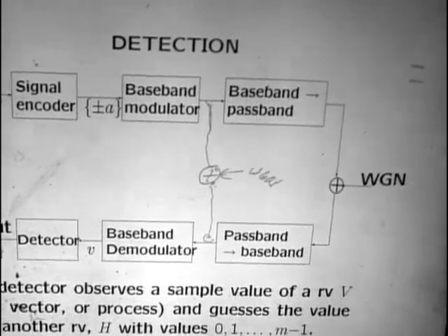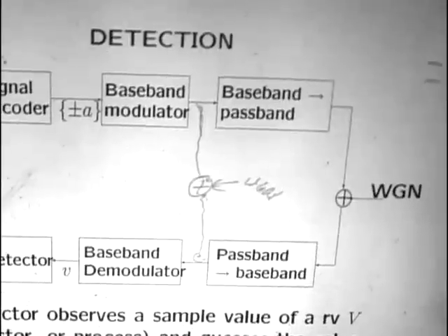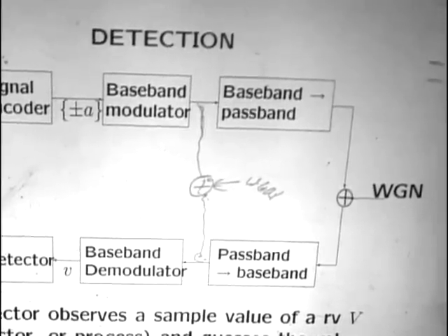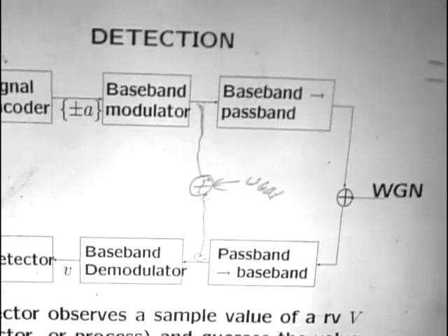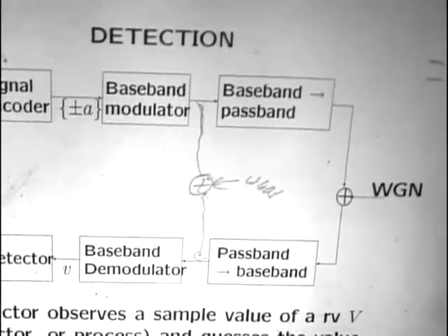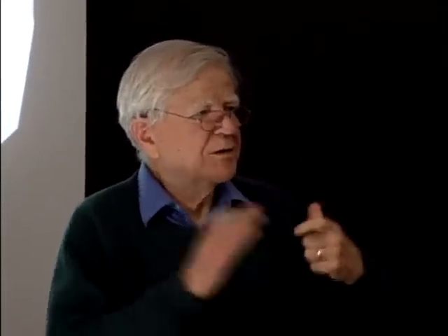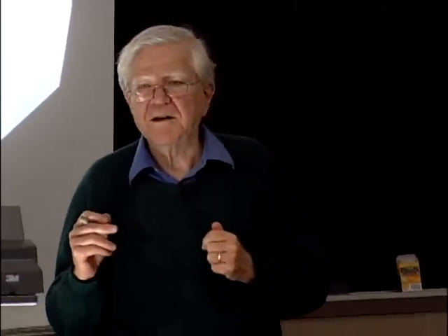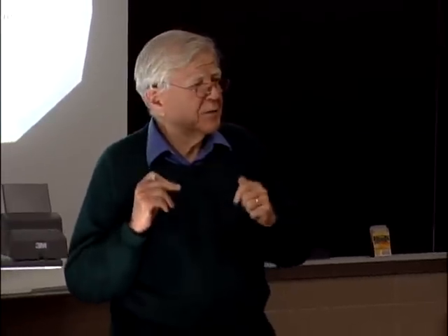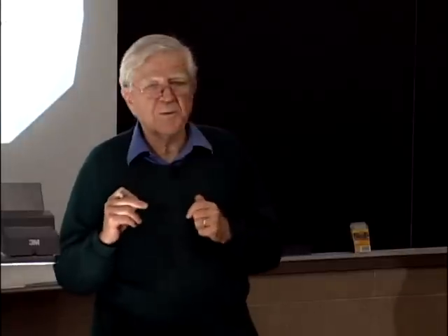We said a neat thing to do was to use a square root of Nyquist pulse at the transmitter. When you use a square root of Nyquist pulse at the transmitter, you have orthogonality between the pulse and all of its shifts. Well, now we don't much care about the orthogonality between the pulse and all of its shifts because we're only sending this one bit anyway. But it sort of looks like we're going to be able to put that back in a nice, convenient way.